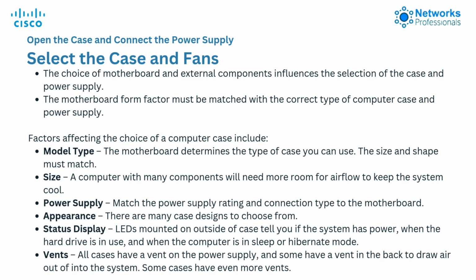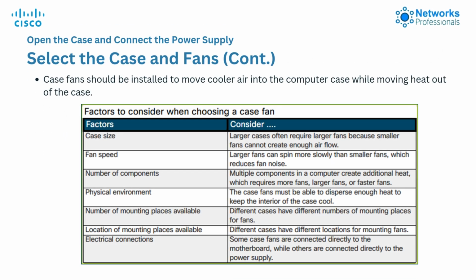Vents. All cases have a vent on the power supply, and some have a vent in the back to draw air out of the system. Some cases have even more vents. Open the case and connect the power supply. Select the case and fans. Case fans should be installed to move cooler air into the computer case while moving heat out of the case. Factors to consider when choosing a case fan.